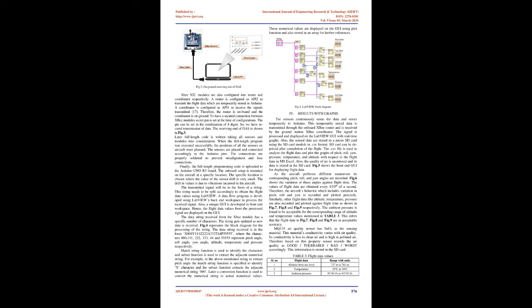5. Barometric pressure and temperature sensor: the BMP180 barometric pressure sensor is used to measure barometric pressure, temperature, and altitude together. It has an I2C interface with a pressure range of 30,000 Pa to 110,000 Pa and the corresponding altitude range of +9,000 m to -500 m.